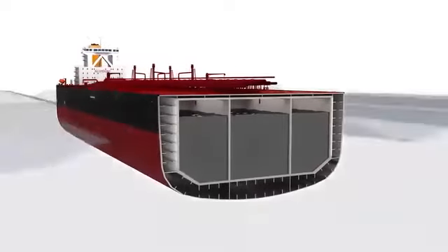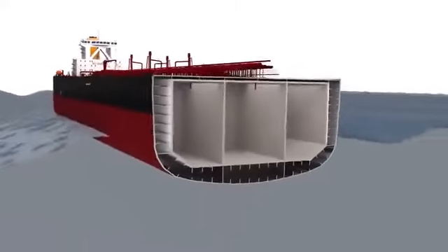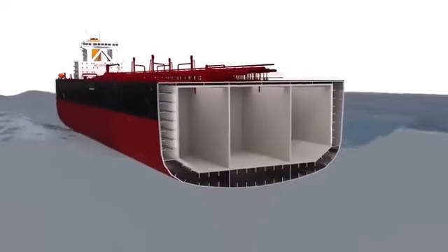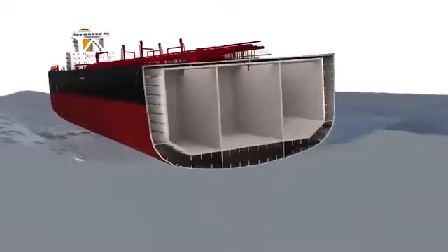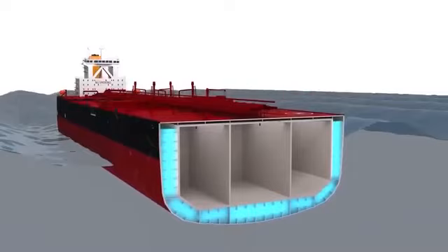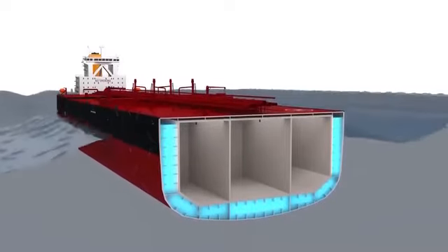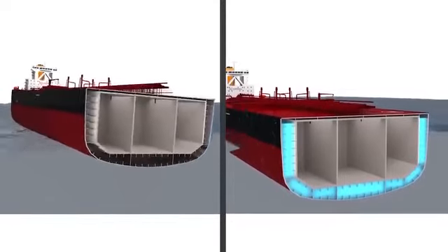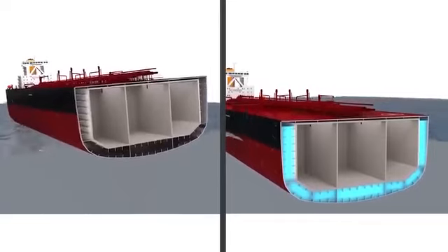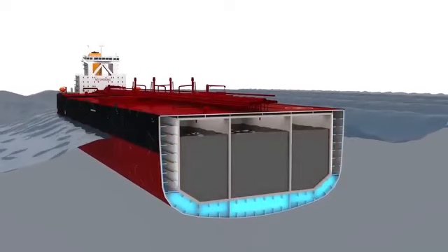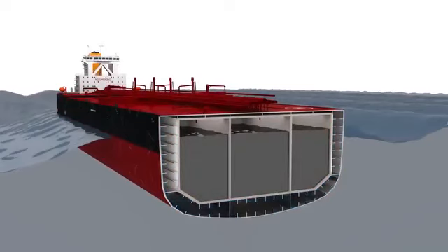When not carrying oil, the tanker doesn't have enough weight to counter the buoyancy and will easily be moved by the waves. Without stability, it will be difficult for crew members to work and live. To be well stabilized, the bottom part of the vessel needs to be submerged under the water by filling the water ballast tanks. When oil is loaded, the ballast tank will discharge its water back to the sea to keep the ship from being too heavily loaded.